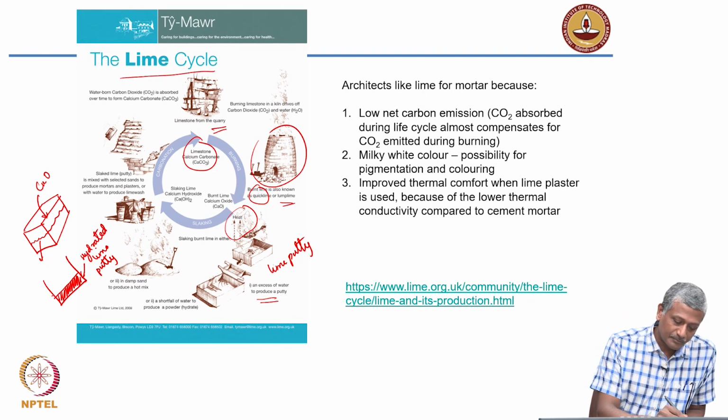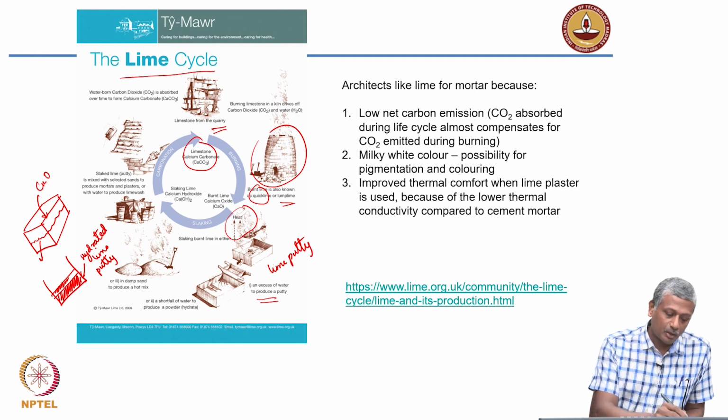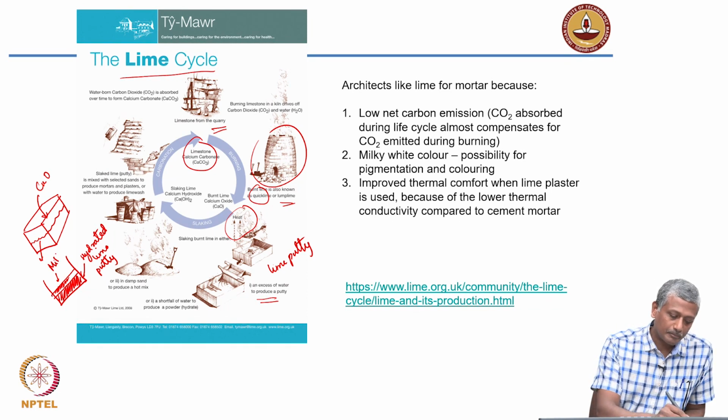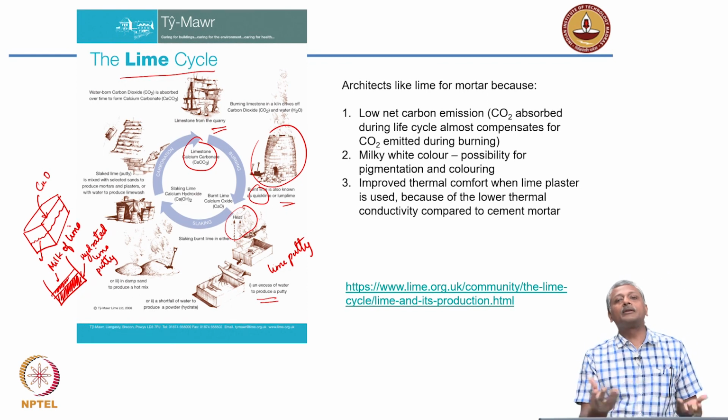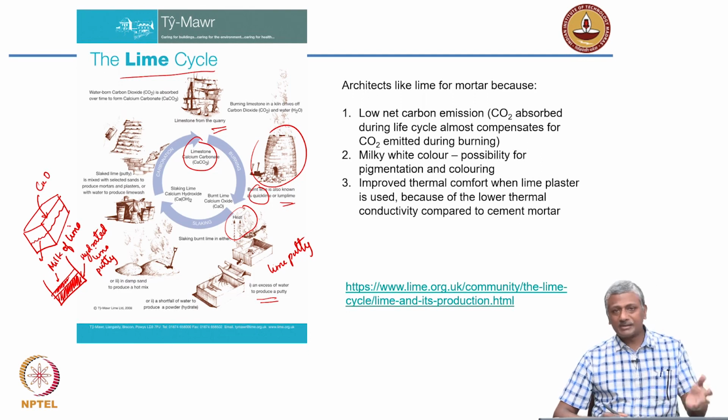On top of that, you may have thinner layers of lime. You may not really have the nice thick calcium hydroxide that is needed for building construction. And on top of that, you also get what is called the milk of lime. That is almost like a white colored liquid that you get right on top. So lime water or milk of lime can be used for your whitewashing application, for instance. There are several different ways in which you can utilize slaked lime.